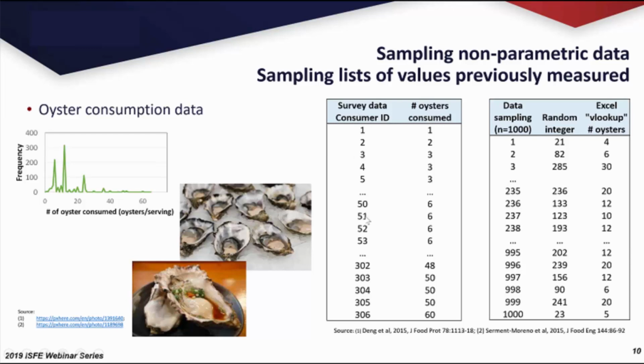So if I do a deterministic analysis, this would be the film permeance that I will need to use. So I'll go to the supplier and say, I want packaging material with this property. Okay, they will understand what you want. If I do a probabilistic analysis of this value estimated deterministically, again, there is about a 50% probability of failure. And I'm considering these two variabilities again, the packaging film variability and the initial water activity variability. The mean values are the same.